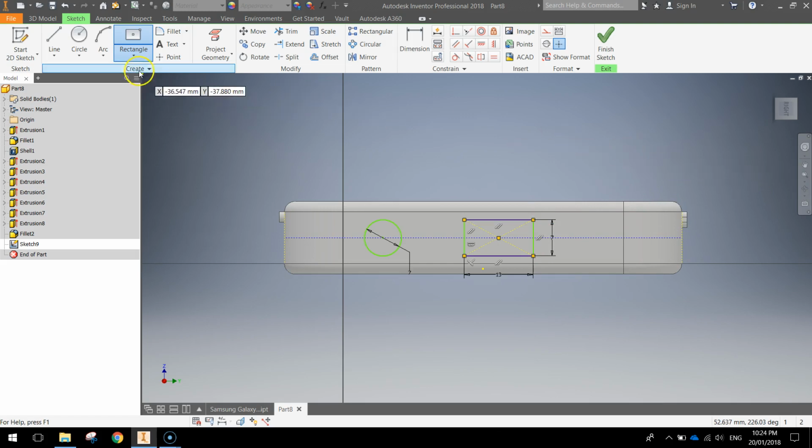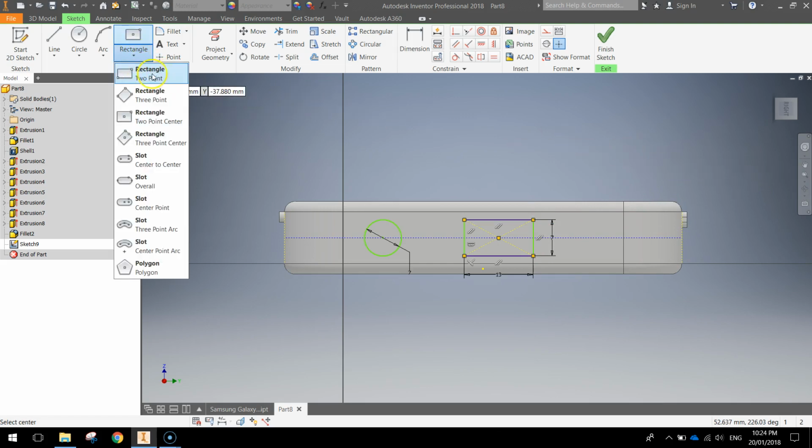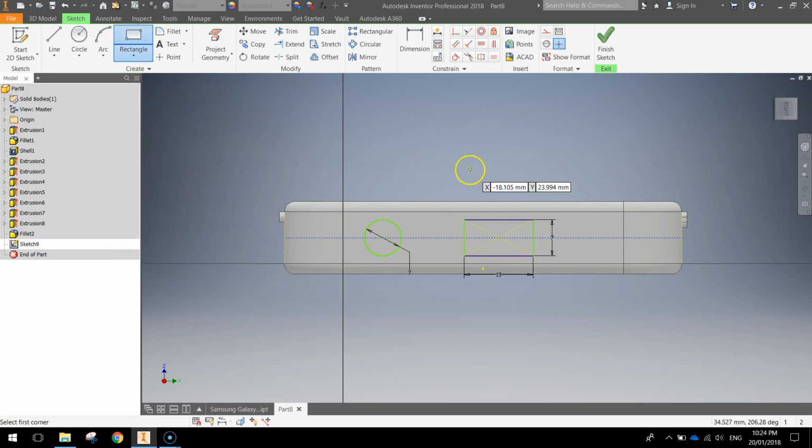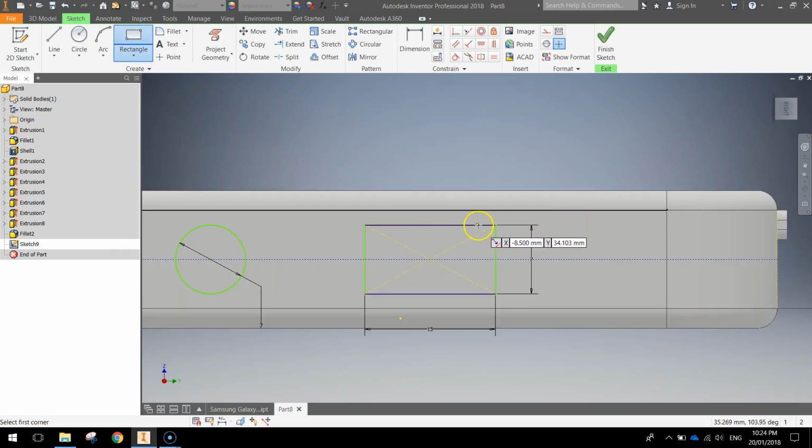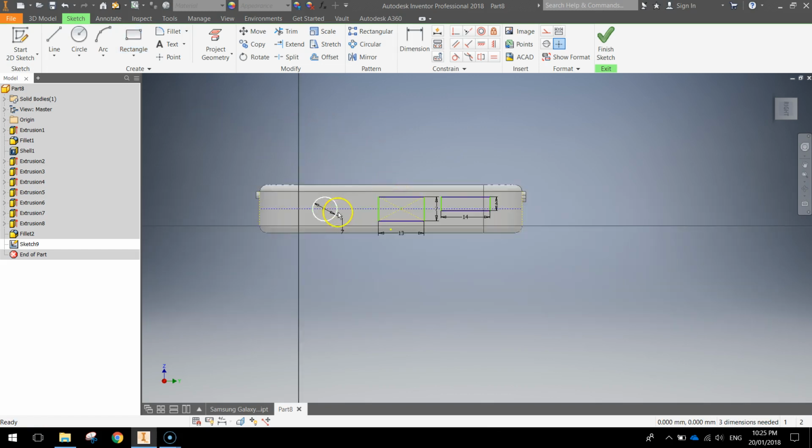Alright, that looks good. We're going to go up and choose a 2-point rectangle now. I know it's a bit confusing. What we're going to do is make sure it starts level with the top of this rectangle, so you can just use your guides to get it right. Click, drag out. This one is going to be 4 high by 14 wide. We'll press enter. So you've now got 3 shapes. Just press escape to turn those tools off. You've got a circle, rectangle, rectangle.